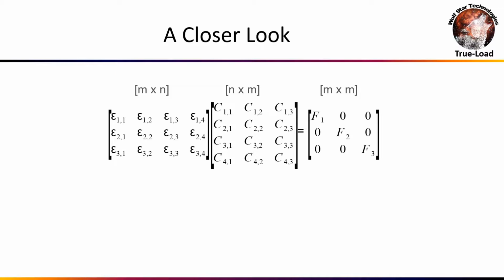What TrueLoad will be doing is essentially called a Craig-Bampton analysis. It would be doing the flexible body response based on the mode shapes, and it would be doing the ground interactions based on the unit displacements. So we get a complete characterization of the dynamic environment from just a handful of strain gauges. This is very, very powerful stuff.